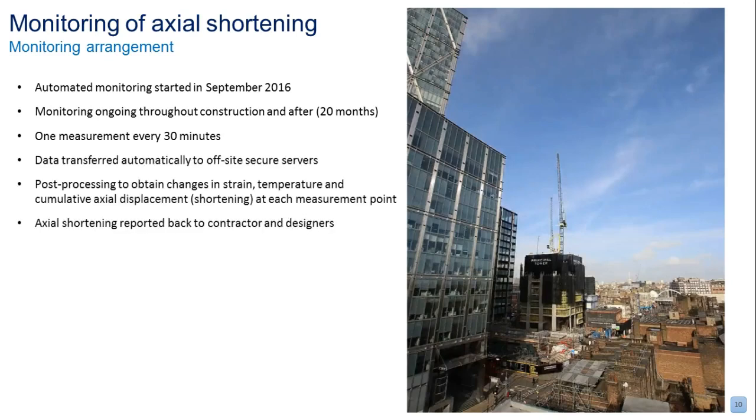Those data were transferred automatically to an offsite server. They were post-processed, changed into axial shortening of each point along the height of the building relative to the ground floor, and communicated with the contractor so that they could review their predictions and adjust the levels going forward accordingly.